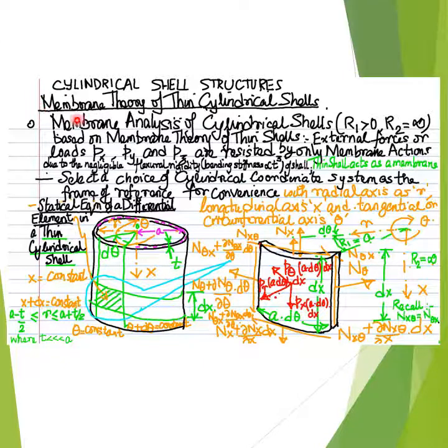In other words, the theoretical formulations that are based on the application of the statical force equilibrium equations for the solution of the unknown internal in-plane or membrane actions Nx, Ny, and Nyx or Nxy in a thin cylindrical shell element based on mechanics constitute the membrane theory of thin cylindrical shells,